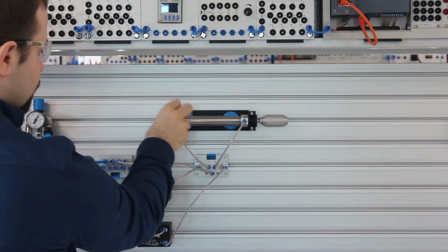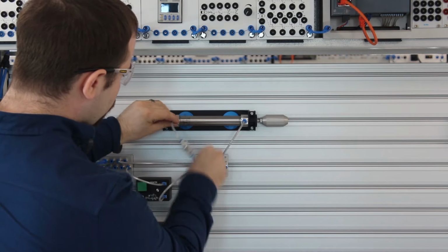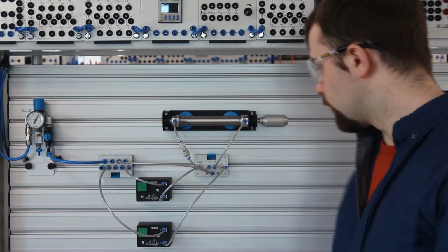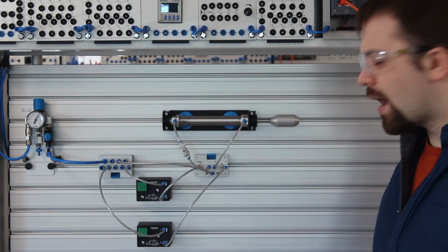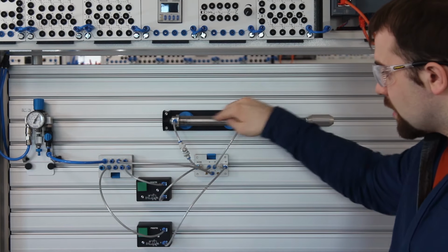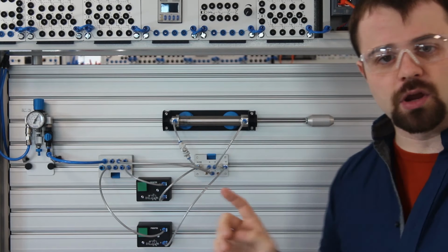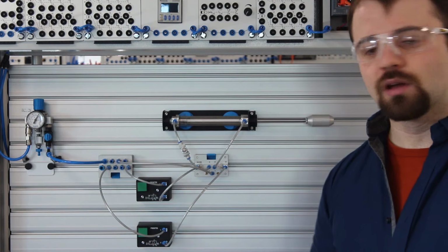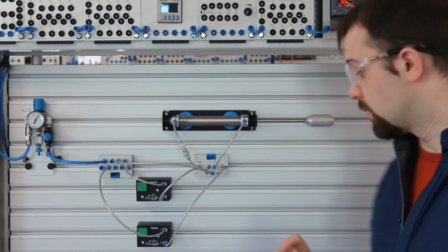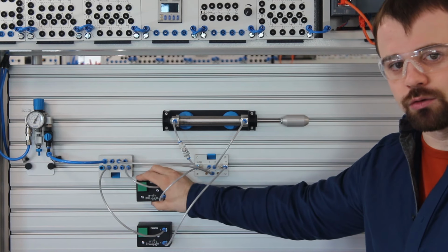Let's turn off the air supply. Swap that out. Arrows going towards the cylinder. Turn on the air supply. And let's have a look at what happens. When I push this button, now we have a slow cylinder movement. When I push the other button, the air that is inside the cylinder is going to exhaust out of this pipe, back through the flow restrictor, but because the arrows are pointing towards the cylinder, it's just going to go straight through, remember the ball valve inside, so there will be no restriction on the backward speed. So, quick back and slow out.